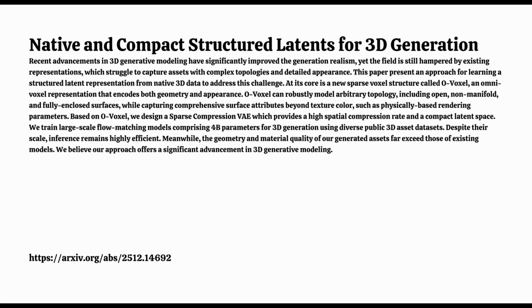And the sources point out that they didn't just use a standard QEF, they made two critical modifications. This must be where the geometric fidelity for complex objects comes from, right? That is the insight. To improve the modeling of difficult open shapes like that sheet of paper or a complex boundary, they introduced two additional error terms into the QEF calculation. The first one is specifically for boundary edges.